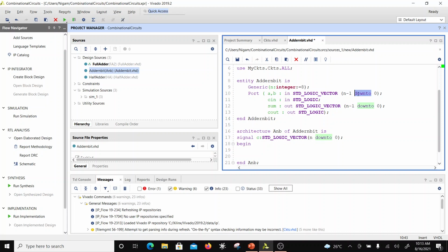Now this can also be used for connecting to buses and flipping the entire word. So I can have two buses which are defined, one as n minus 1 down to 0, the other one as 0 to n minus 1, and when I connect them, this flipping would be automatic. So basically for flipping, you do not have to do anything but just connect it differently, right? So I'm not going to go into details of all that. Many books basically spend a lot of time doing that kind of stuff, so it is counterproductive. So let's go ahead and do this.